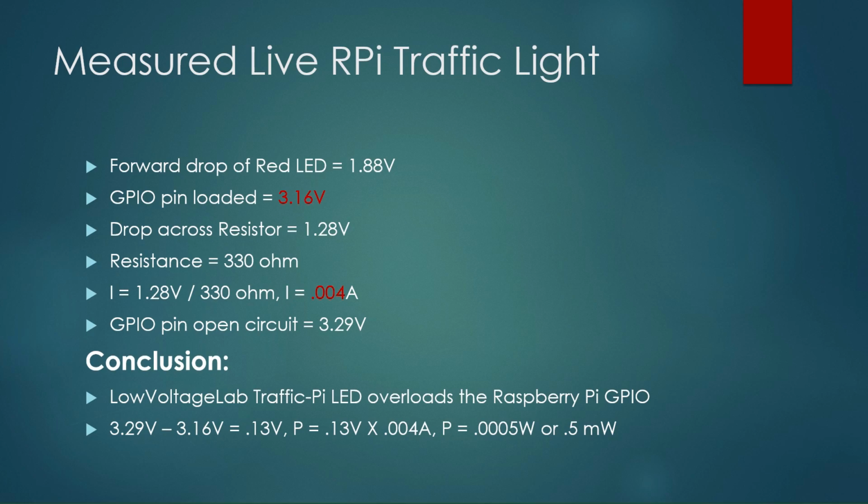So we take the 3.29 open circuit voltage and subtract from that the 3.16 volts of the circuit loaded, and we get 0.13 volts.